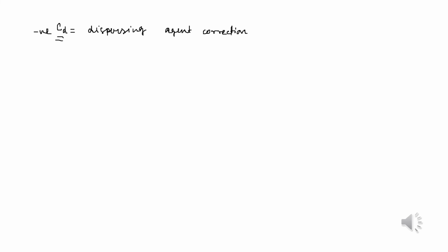The next correction is due to the meniscus. As we know, the soil suspension is opaque, therefore the hydrometer reading corresponds to the upper level of the meniscus, which shouldn't be the case. The reading should always correspond to the lower meniscus, right? So a correction which we call the meniscus correction, CM, is added to the hydrometer reading, right?